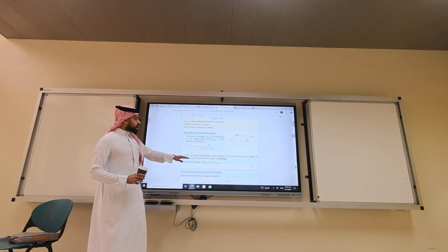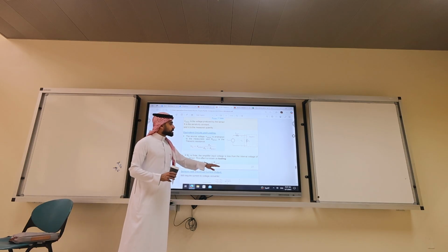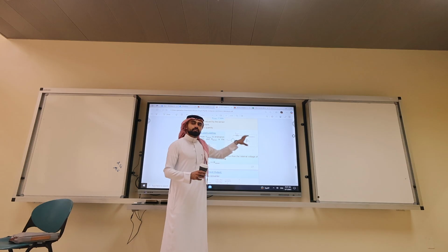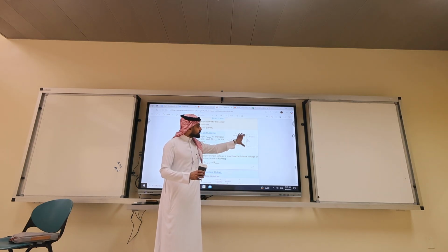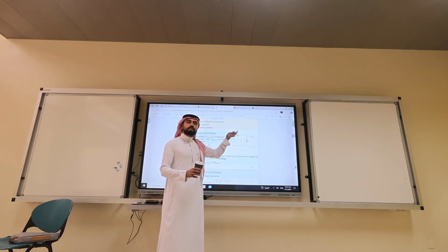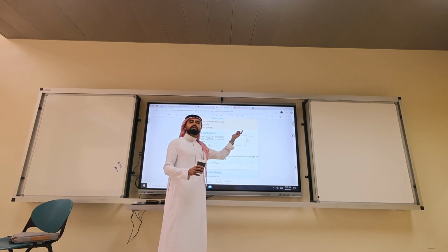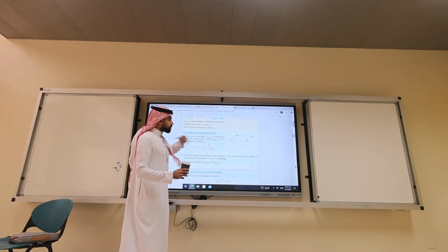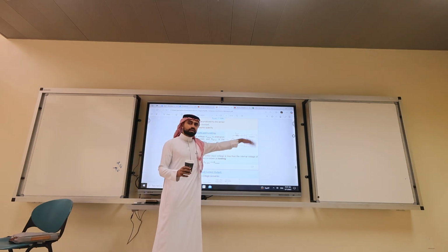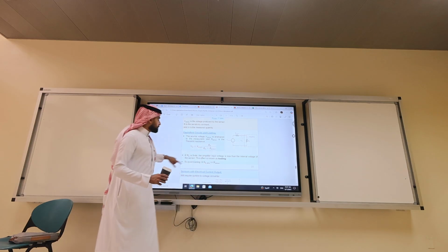Of course, you want to have your input impedance much larger than the sensor. To calibrate it properly, you want this ratio larger than the impedance of the sensor. Maybe 9K, 1K, or 15K, 2K. You don't want it to have 1K and 1K. Then you will get 50% of the voltage. Then you will have what? A weak signal. So the R for the amplifier after the sensor, you want to have large input impedance.